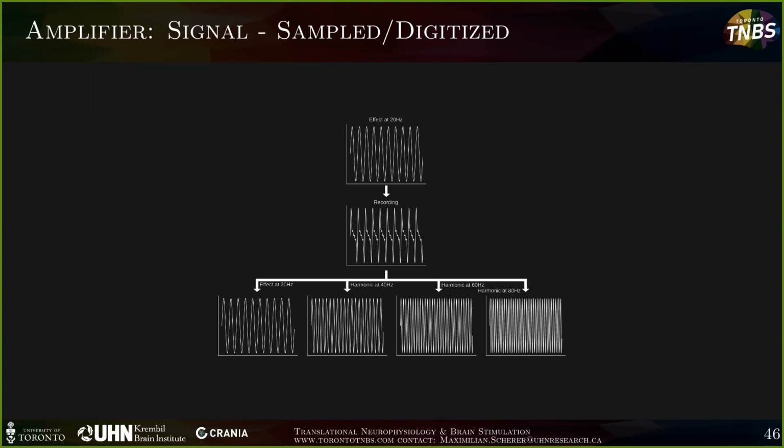And that's quite common if you look into deep brain stimulation artifact, which usually happens at 130 hertz. You're quite likely to see those at 260, 390, and so on. Or you're also likely to see the same effect if you're recording even somewhat in the vicinity of a power outlet. You're going to have line noise, but not only at 60, you're going to have it at 120, 180, 240, all over the signal, basically. And that's called harmonic distortion. Those are more difficult to get rid of.